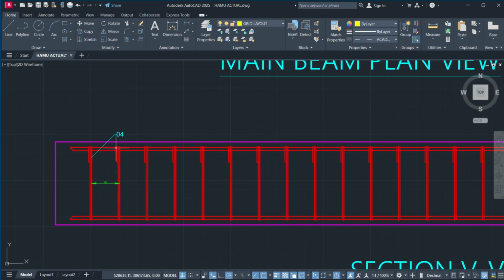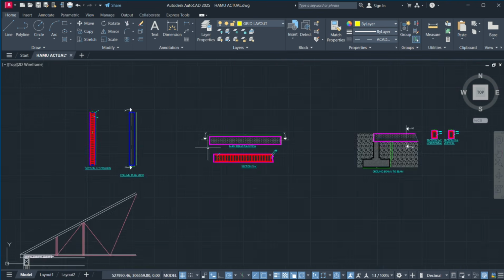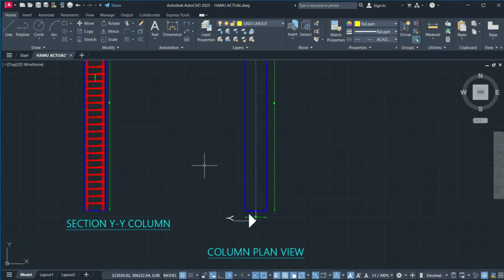Then when you section it, you need now to show these ties and these rods that are actually going in this direction. The same procedure you had done on the foundation, it's the same procedure that you're going to do in this one, but in a horizontal sense, sorry. So they're going to run in this direction, then you're going to have your ties tied to them, just like this.